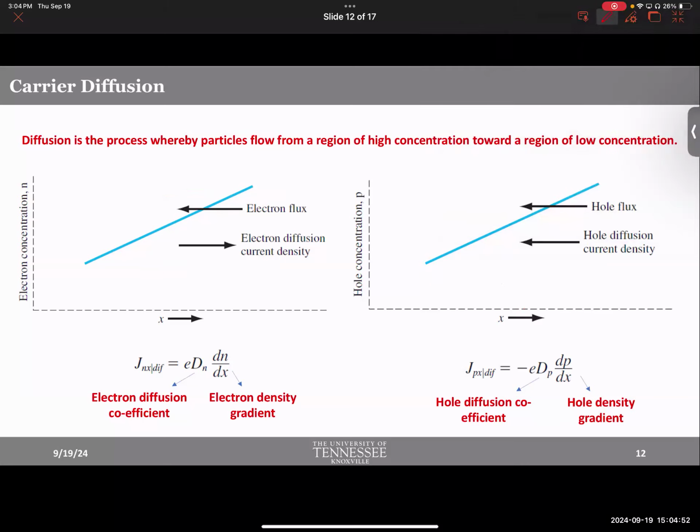In electronic devices, we engineer ways, folks, honestly, I know this doesn't sound exciting. This is how people start thinking about new devices. Here is what you need. We need to create more density here, less density there, so that current will flow here. So let's go back and use different heterojunctions, different materials to create a phenomenon that will lead to a pile up of electrons here and less electron concentration somewhere else.